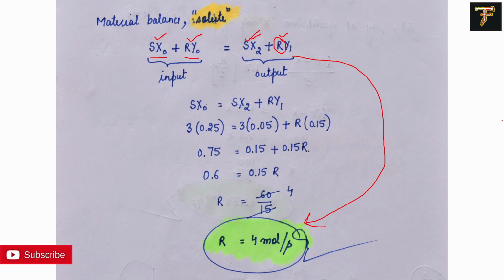So all you have to be aware of is how to read the equilibrium curve. You should know that the steam, or any other gaseous form, that is about to leave the column from the top is always in equilibrium with the liquid that is about to enter the column. If you have that, you just go to the curve, directly find the composition, and you're good to go.